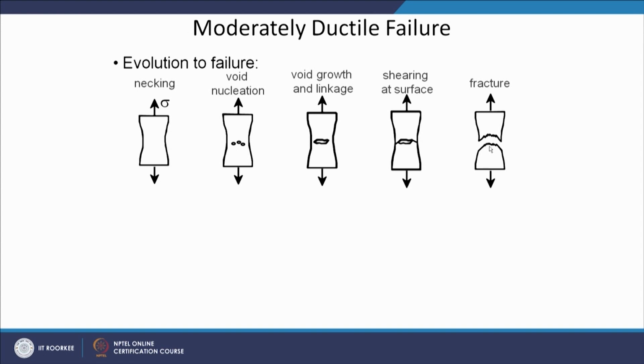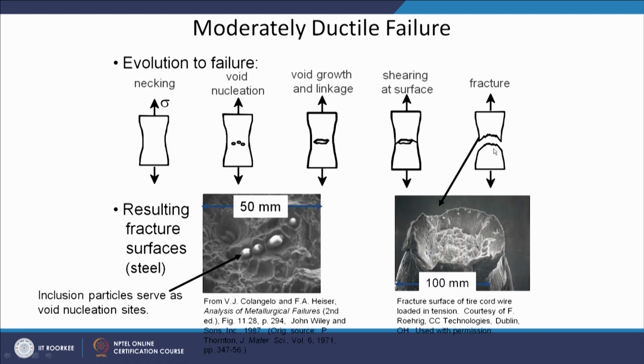So, here if we see this one, the flat fracture is basically a typical indicator of ductile fracture, but here the flat fracture zone is being formed by the nucleation of voids, and their subsequent growth is leading to this zone. And that is why it is important to understand the microscopic mechanism of the fracture.